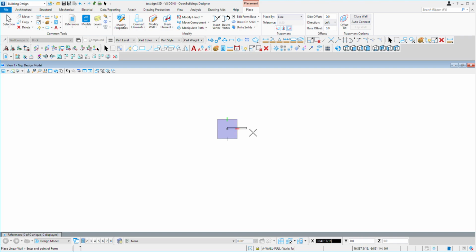So if I place like this, you can move or place your wall in whatever direction you want. If I enter this direction, the software automatically freezes this direction. Here you can see that rectangle, we call this AccuDraw.